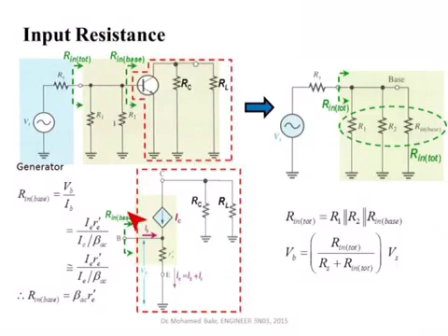Well, let's take a look at this figure here. This is the model of the transistor. So this is the collector, this is the emitter, this is the base. I replace the transistor by a current-controlled current source and a small resistance Re dash. We already know what Re dash is from the DC analysis, and we know what beta is for this source. Now my target is to determine this base resistance. So I'm considering only this part here. I'm trying actually to find the Thevenin equivalent looking into this part.